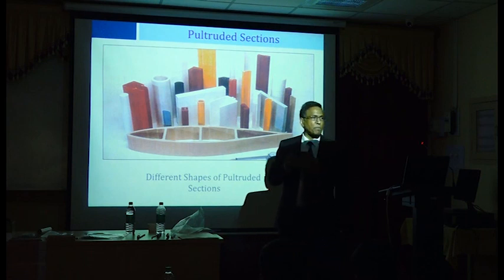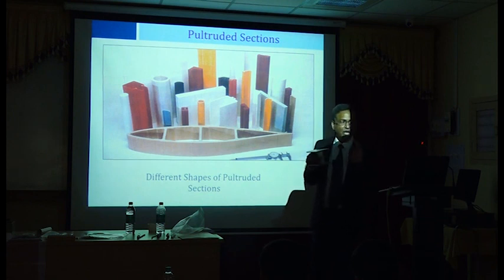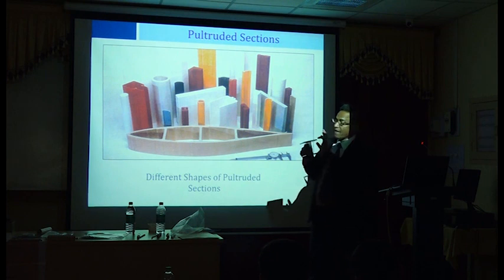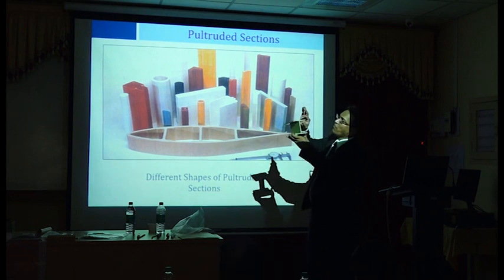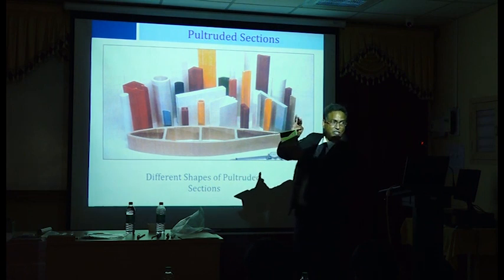Details. If you see steel profiles, the web thickness is designed to not buckle for shear, but it's very, very thin. Most of the moment is carried by the flanges, right? Top flange and bottom flange. Therefore, you will have very thick flanges for steel sections.